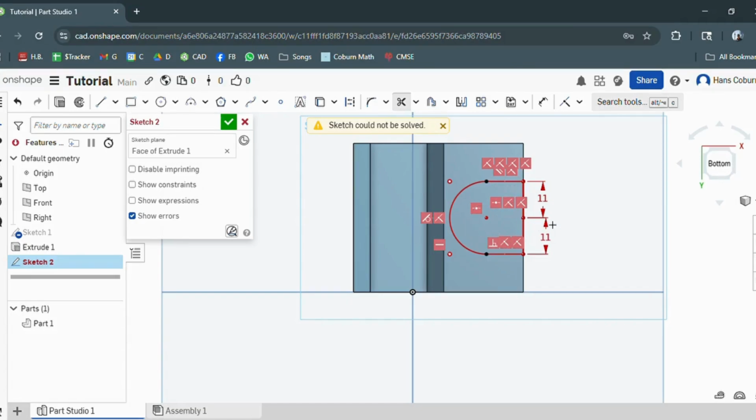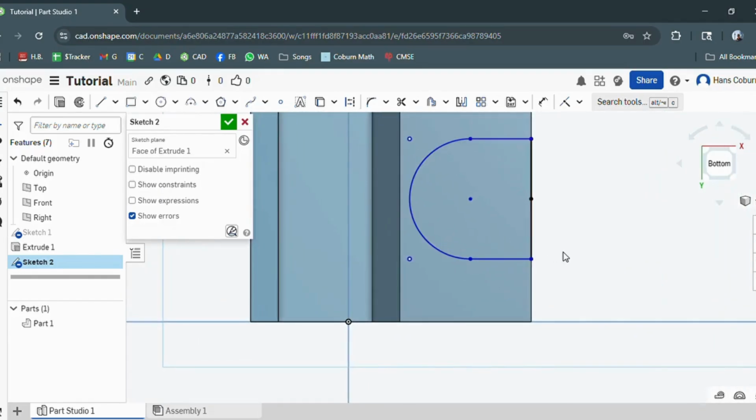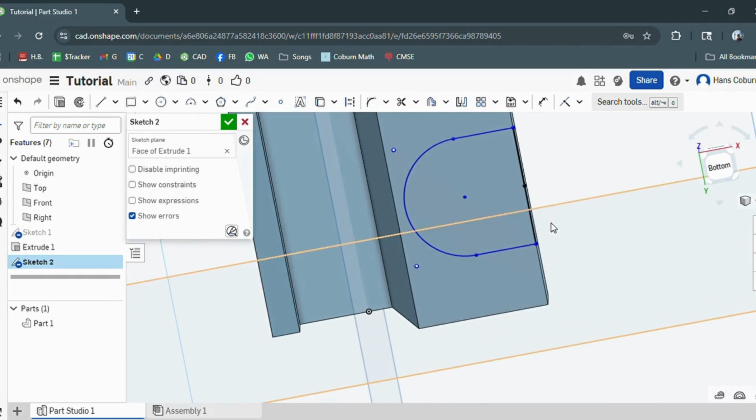Okay, there we go. Okay, now it's saying I've got an issue here. I'm going to delete these so that it's happy with me. In that case, it was trying to fix my circle to a dimension that I had already set, and they were contradicting slightly. And I'm not too worried about that being perfect, because I think it's fine. It just was having issues. Yeah, see, that's still 11. So we're all good. Just having trouble with how the circle was rendered.